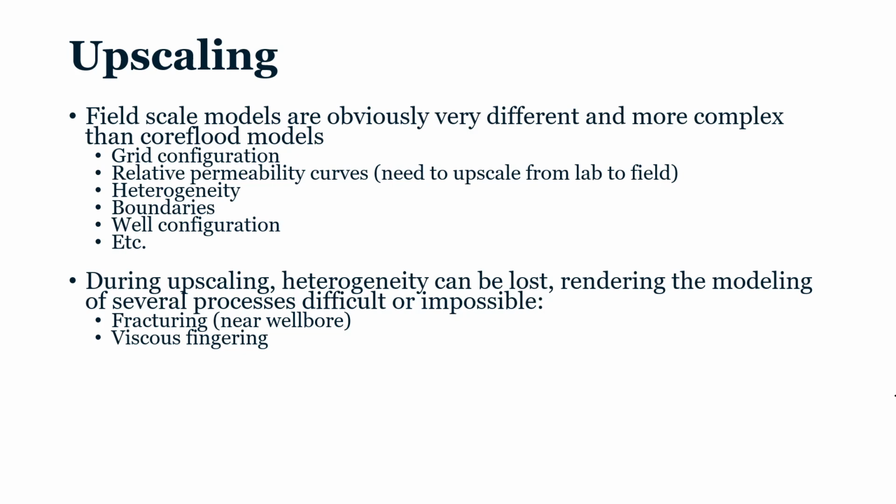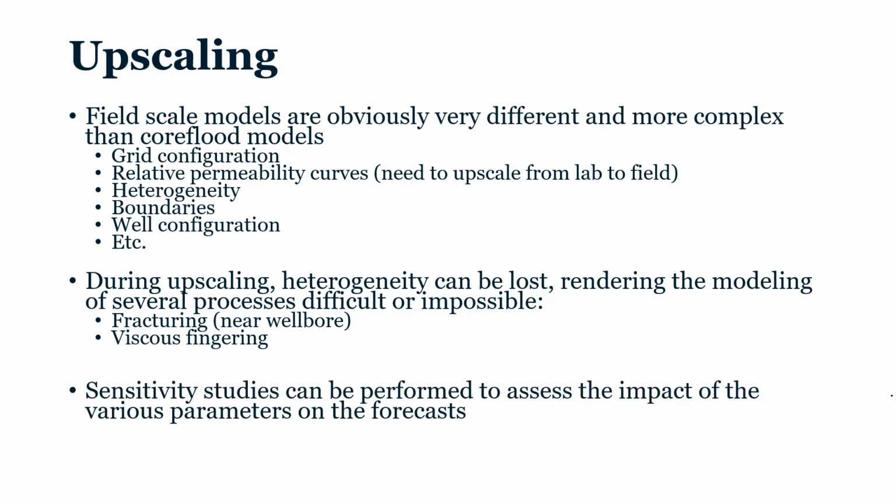But when you start looking, the reason is that at 20 centipoise, the injectivity decreases so much in the simulation that the mass balance means you don't produce any oil. But again, is it true in the field? Will I see injectivity decrease if I go from 10 to 20 centipoise? Maybe not. So once again, it's a very critical point to bear in mind.